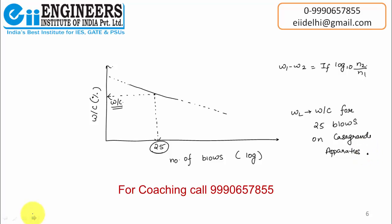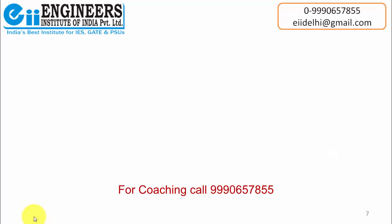Or we can also say that it is defined as the minimum water content at which a part of a soil which is cut by a groove will flow together for a distance of 13 mm under the impact of 25 blows. Okay, now we'll go to the next term. What was the next term? Plastic limit. Plastic limit determination.